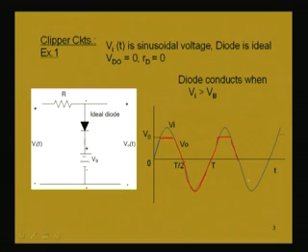So, you just note here that the upper portion of the input voltage is now clipped. We are getting an output voltage V naught which is like this. So, this portion is just clipped away from the input voltage. So, this is a very simple example of a clipper circuit. Here you notice that we are still assuming that the diode is ideal without any voltage drop when it conducts